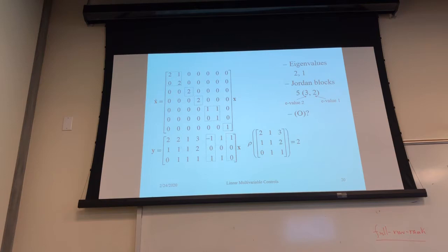Then next we are going to check this one, and it's full column rank. The number of columns is 2, and the rank is 2. It's called full column rank. So this is observable, and overall it is not observable. I hope this example gives you different Js, and that you can follow the procedure to tell the controllability and observability of the system.